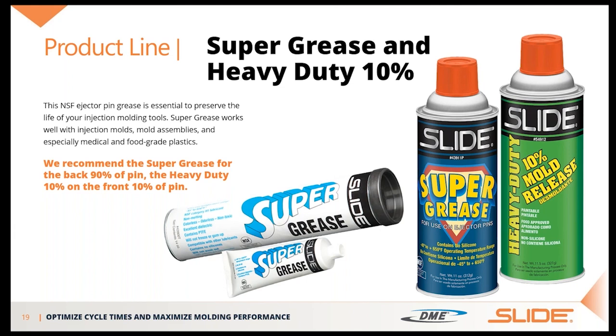It's a fantastic product. The story I've got for that one is one of those where it seems like duh, but sometimes people don't know, and you've got to help figure out what the problem is. They were saying that the grease they were using was underperforming and it was turning black. So we did a little investigative work. They were using a lithium grease, and the temperature rating was 225 Fahrenheit, and they needed between 350 and 500.